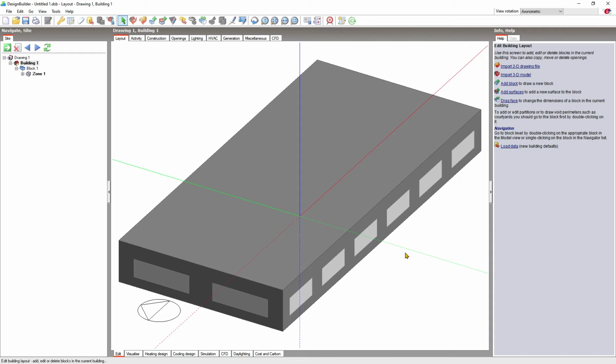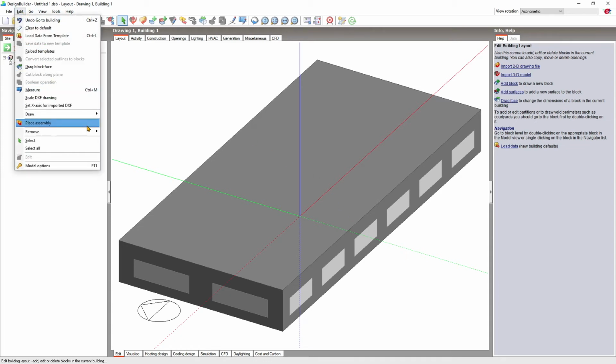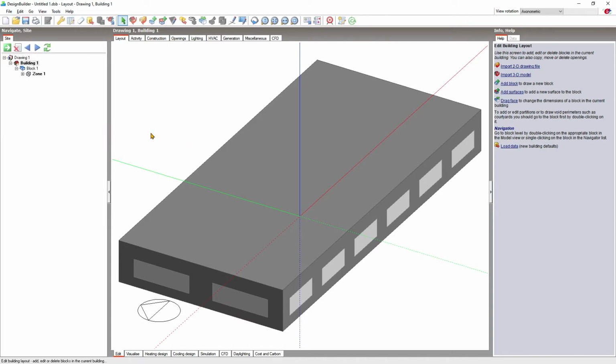You can move imported floor plans onto other surfaces in the model after selecting them. You can also import facade drawings. Simply import them as you would a floor plan, then select the imported facade drawing and move it onto a vertical surface to use as a guide for drawing windows and doors onto surfaces, for example. You can remove an imported floor plan via the Edit menu and selecting Remove DXF Data.